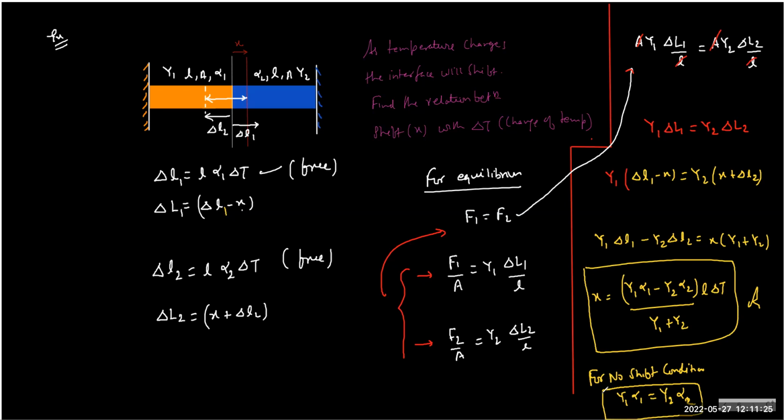Oh, yeah, sir. So that is why in case of railway tracks, the gap is left after some length. Because if you don't keep the gap, due to the thermal expansion, it will try to develop stress, and the stress may lead to the deformation also. So here we are preventing the distortion in the shape.